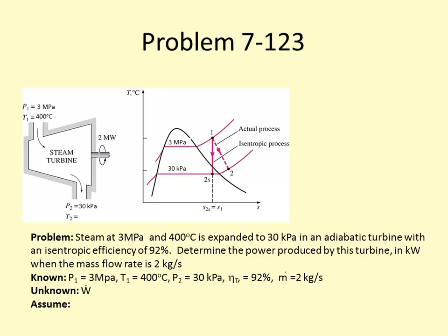So now we can calculate our isentropic case for the enthalpy, which is equal to H sub F plus X times H sub FG. H sub F is 289.27 plus 0.8763 times 2335.3. So we find H2S is equal to 2335.7. Wait a minute. Oh, that's right. That's HFG, not HG. Okay.